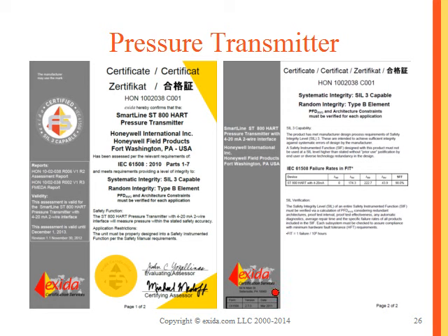You see template information on the back side. You see failure rates. And then you see the overall product assessment levels and the assessors, including the safety function. So in this case, the transmitter is only for the 4-20 milliamp 2-wire interface. That is part of the scope. So this particular device can do HART communication, but that HART communication has been determined interference-free or feedback immune, and we have not considered the HART signal as part of the safety function.